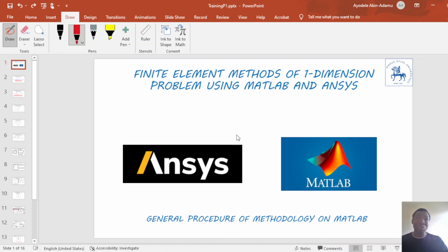I plan to cover two-dimensional problems such as plate analysis using the constant strain triangle element, CST. That's what they call it, the constant strain triangular element. Under the 2D plate analysis, steel plates under loading will be analyzed using the plane stress condition. Also, the 2D finite element procedure will also be applied to beam analysis.